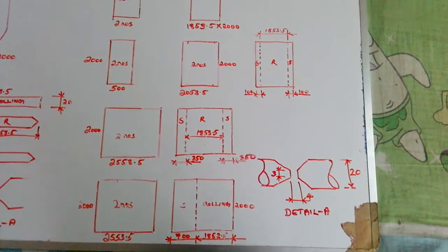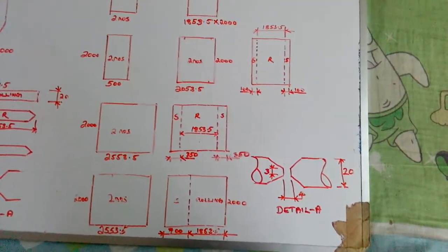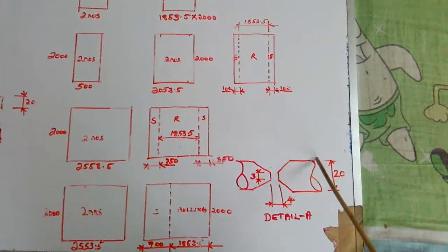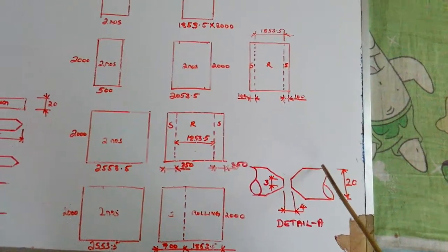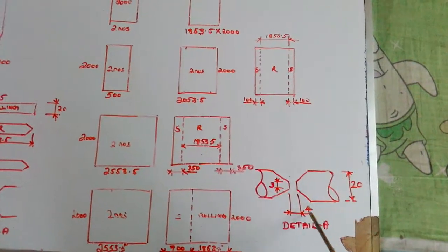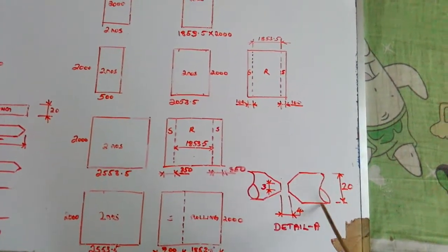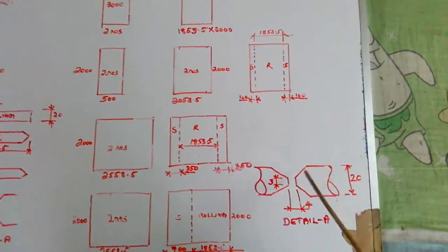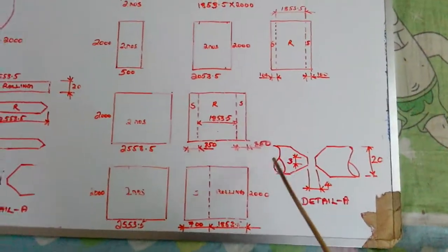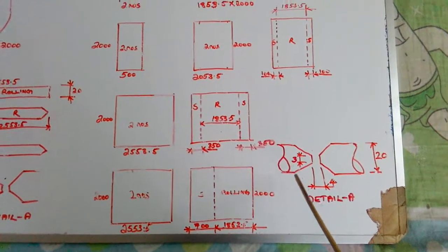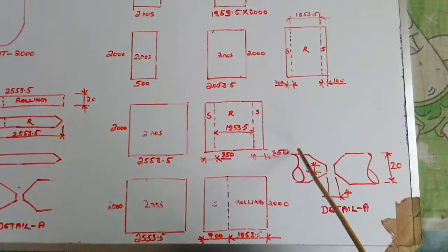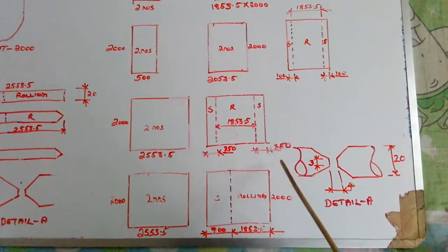We can't indicate it in this drawing. If we can't indicate it in this drawing and it can't be scaled, we have to show this kind of measurement indication in this way. What does it mean? It means these two lines don't stop here, they have more length. I have given the same indication here also. What does it mean? This pair of lines, this indication starts from here and this indication ends here. In between, two lines are going. These two lines are not finishing here.